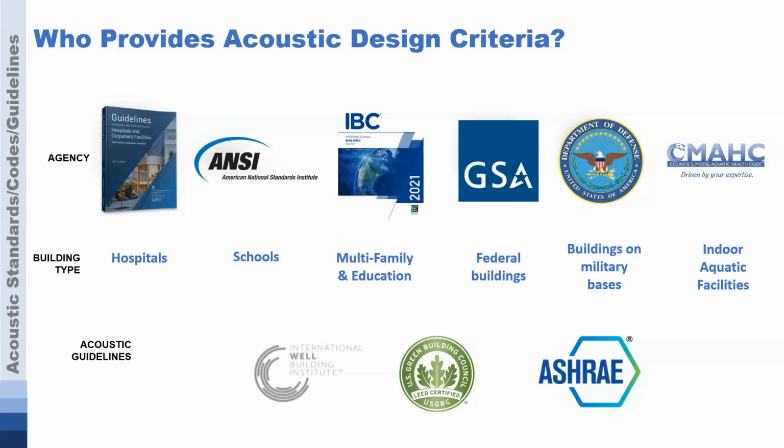For schools, interestingly, just this past year, the Florida Building Code has now incorporated the use of acoustic criteria in the building codes. So now there is actually a multitude of acoustic criteria that are contained in the Florida Building Code for school occupancies. This is also addressed with ANSI S12.60, which was an acoustic standard written in the 90s. That has been very influential in a number of codes and guidelines and criteria.